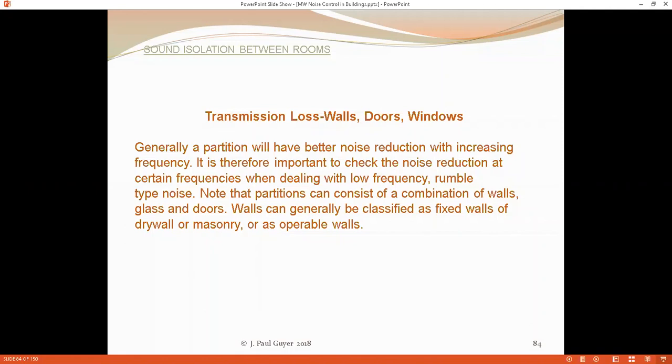So that includes doors and windows and things like that. So you may need to buy doors that are labeled as having an STC rating of 50 or whatever. And these doors' STC ratings, or glazing systems' STC ratings, are all determined by test, Underwriters Laboratories again.